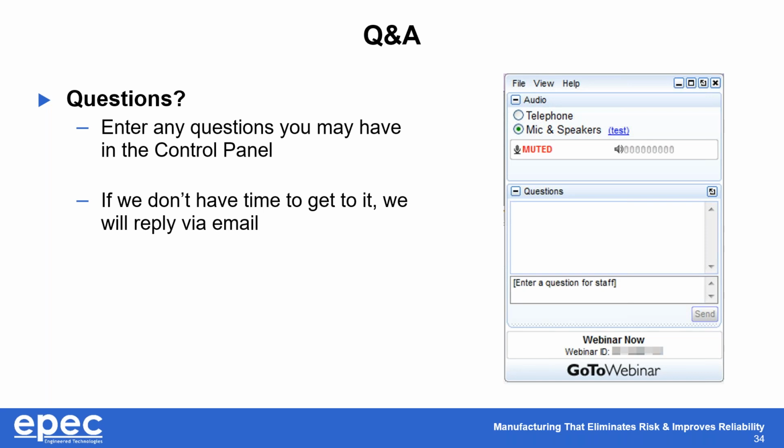One more question here. Do the same cost adders apply to rigid flex? Yes, they do. And for all the features that we talked about here, all of those features for the most part are available on rigid flex parts. But there's some additional ones when we do rigid flex, right? The number one rigid flex challenge you have is the construction, right? And the stack up is probably the biggest challenge that we have with customers.